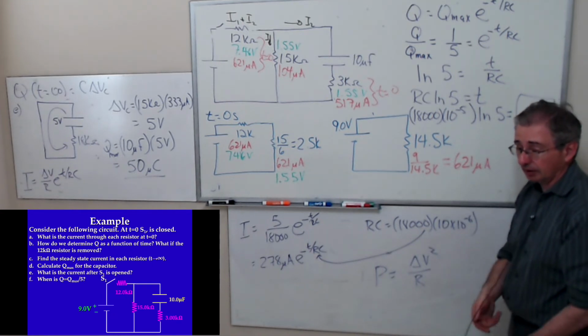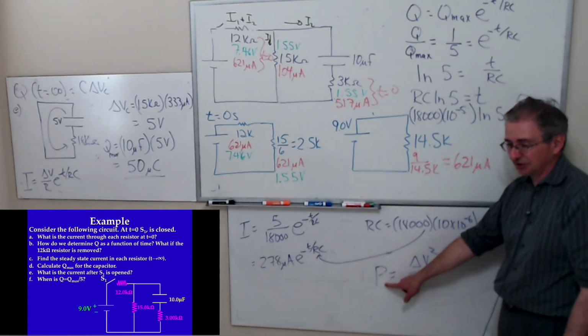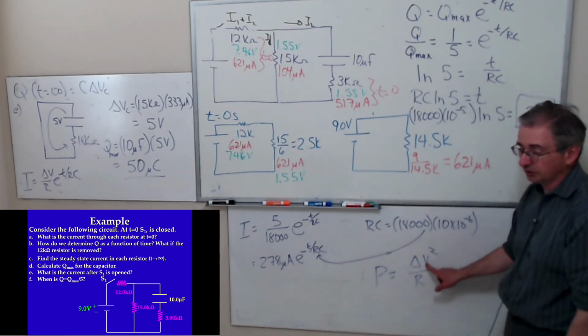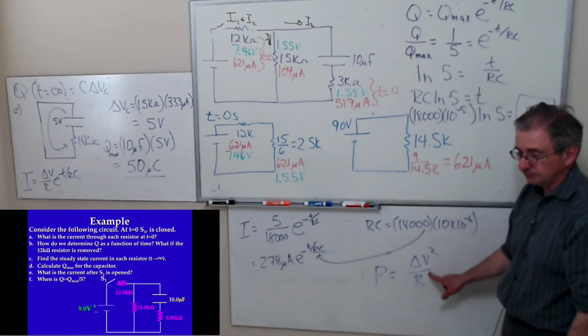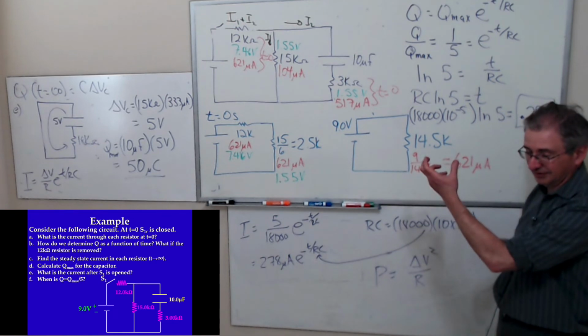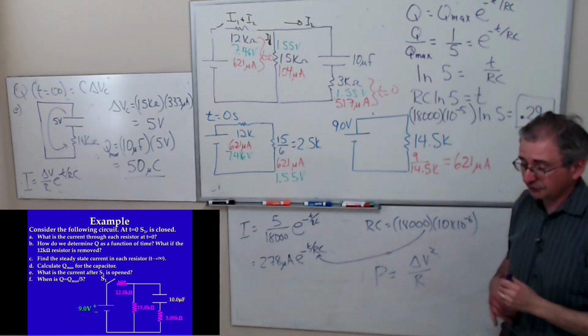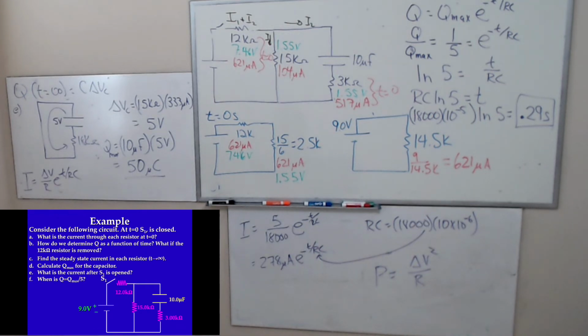You're right about that. But you're confusing two things: the power rating and the power that's used up by the bulb. The power rating of a bulb is always with respect to 120 volts. That's why I'm using this equation. So I'm talking about an isolated light bulb. When you have a single light bulb, the stamp on it assumes 120 volts across it. So that means V is 120.